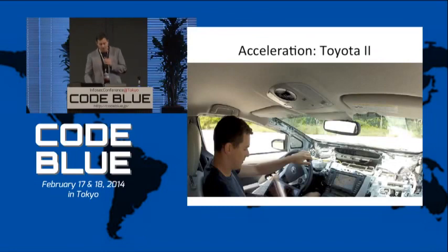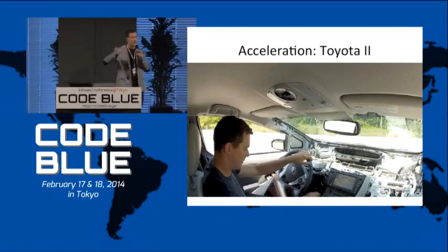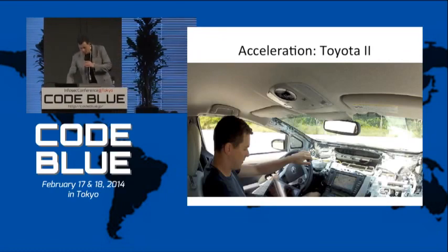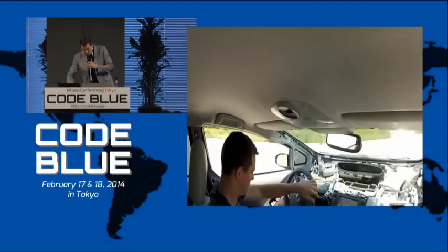Acceleration is another thing that we could do in the Prius, since it was really accelerate by wire. While it was on a segregated CAN bus, we wanted to show that you didn't need to just plug into the diagnostic port. CAN is a pair of twisted wires, CAN high and CAN low. So we just found where that bus was and clipped right in, and we could accelerate the car.